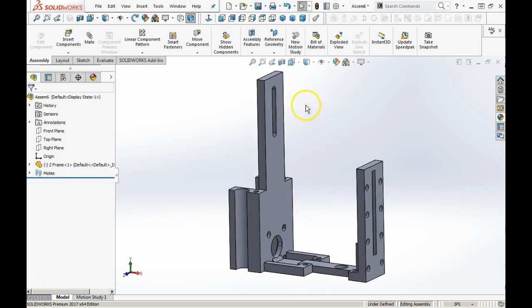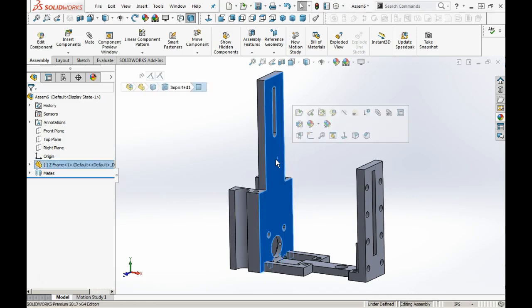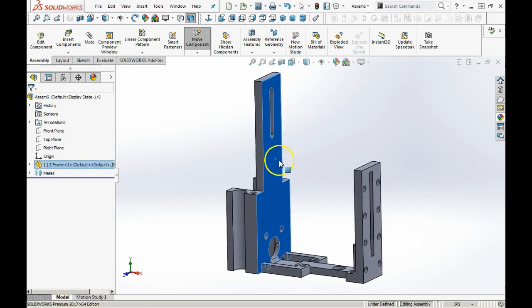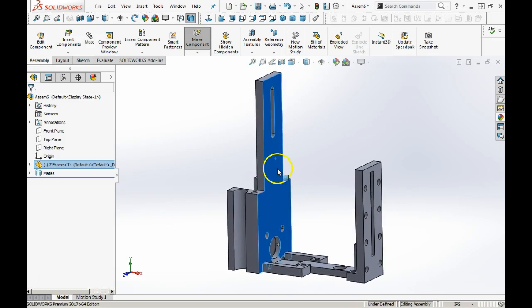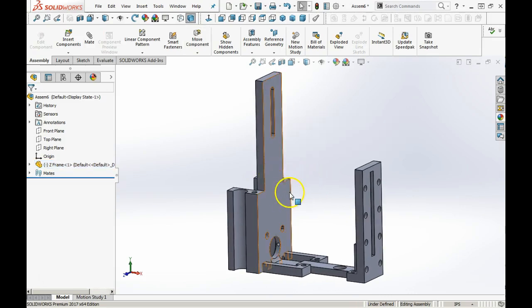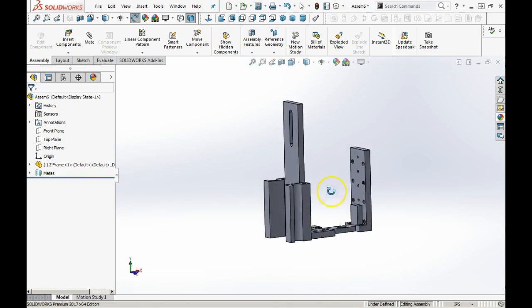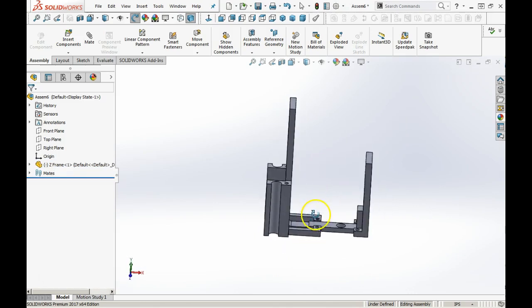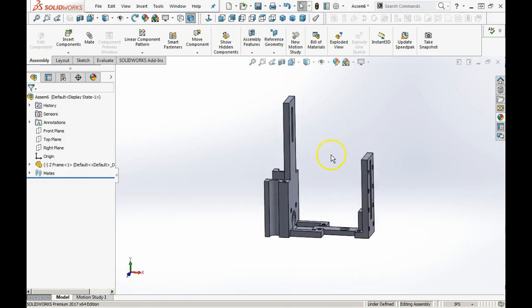So it's real important that you do that little orientation trick. And if you just watch the tape again, you'll see how I did it. Basically, I made sure the part would float. Now, right now, if I click the part, it will try to not move when I do the right-click thing, okay, because it's anchored on all the planes, which is fine because we have to have something that's solid to work with. Okay, I'll pause here for a second.